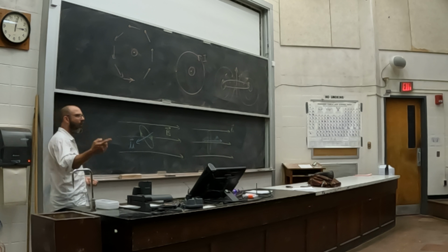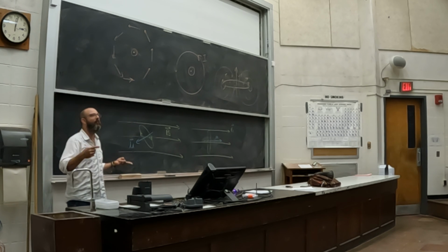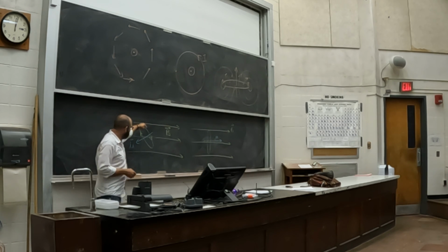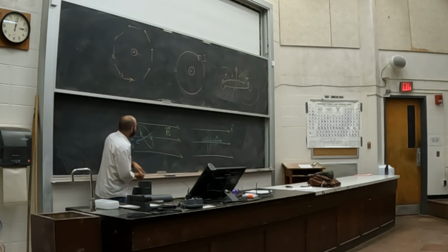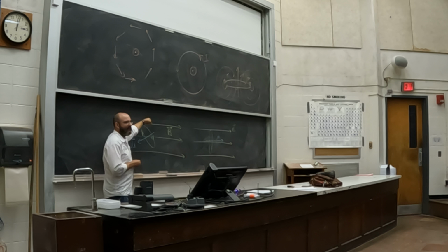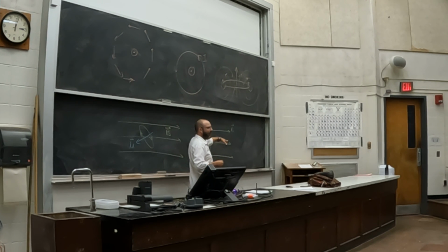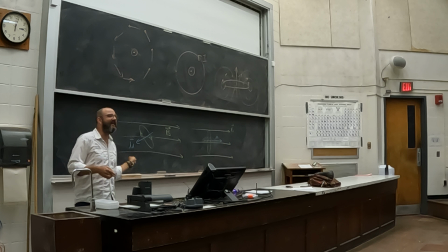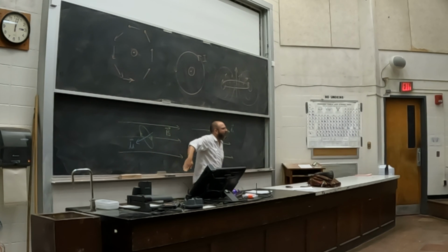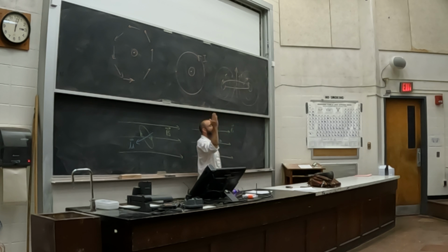You run a current through a coil. That current through the coil produces a magnetic field that looks like this. Then if you let that interact in a background magnetic field, it lines up the vectors. So what happens is if you turn something on, either you turn on the background field, or you turn on the current that produces this field. When you turn it on, if it's in this orientation, it will spin, it will rotate around to this position. Now, here's the kicker. It's not going to stop because this thing has mass, ergo it has inertia. So if it starts out like this, it's going to rotate around to this position, but it keeps on going. Its inertia carries it through to the symmetrical position here.